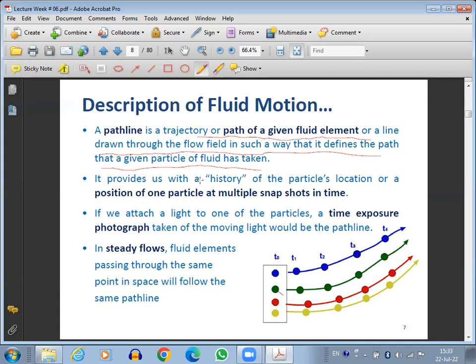They can intersect. If you put in two pieces of tissue paper, it may happen that the two pieces collide with each other somewhere. But the streamlines will not intersect because they are not real lines. We are just making them to show the path. If the fluid is smooth, if the fluid is following the way we want it to flow, then there won't be any intersections.